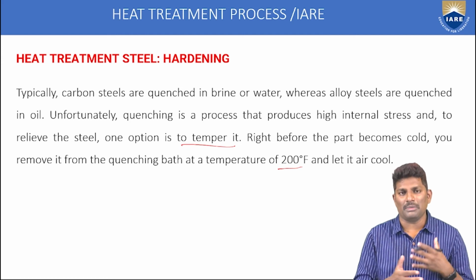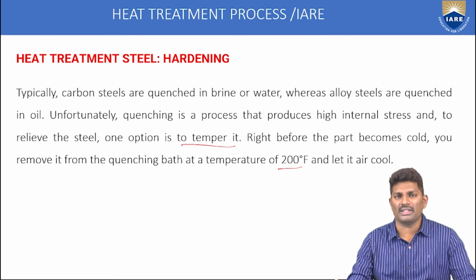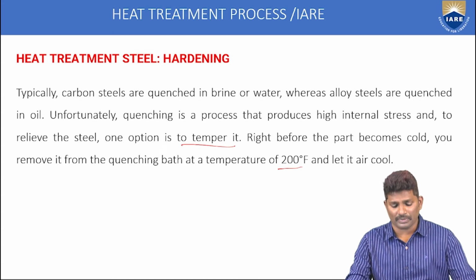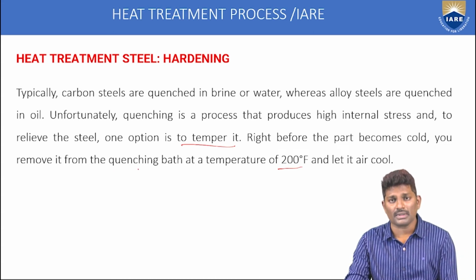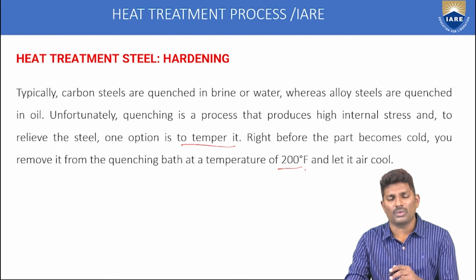So that's what, depending upon the type of material, here what we are doing for the carbon steels, when it is coming to 1000 degrees Fahrenheit, we are trying to cool the system within 1 second. And if it is alloyed with any other element, then beyond 1 second we have to wait and then we have to cool. And again, if it is done with some tempering process, then we have to do the quenching process at 200 degrees centigrade and let it cool with air.